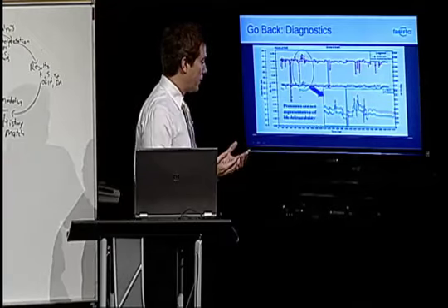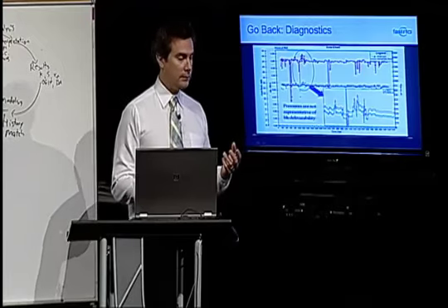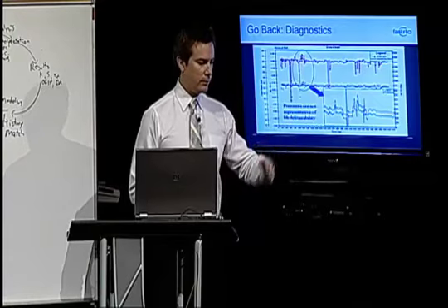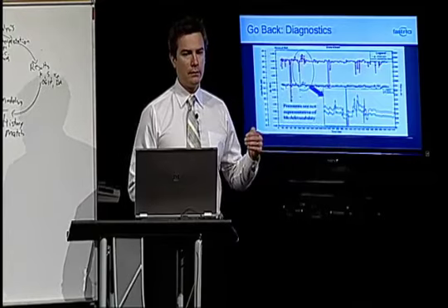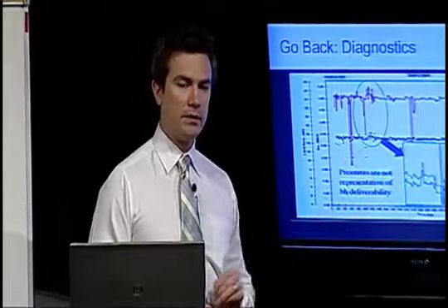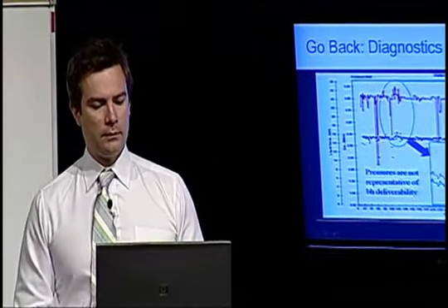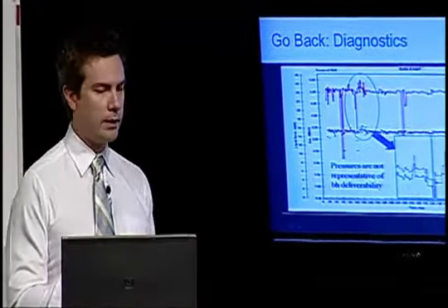Now again, there are other situations where maybe the data isn't measured this way. You might have daily production rates, but the pressures are only measured every week or every month. In that case, you wouldn't be able to do this diagnostic. So you may or may not have problems. The diagnostics will really show you very quickly. If you're doing it properly, you'll probably end up with more questions than you had at the beginning. But certainly you need to investigate those things and make sure that you can make sense out of them.